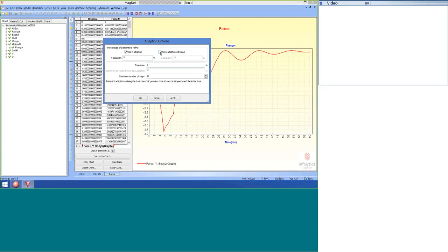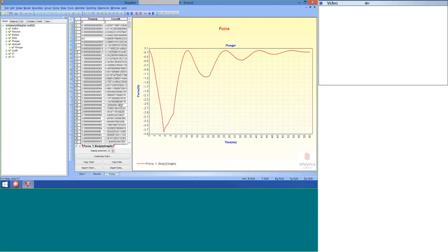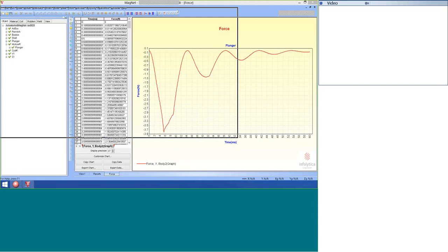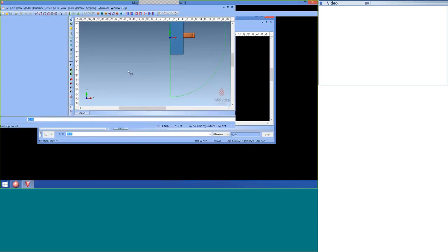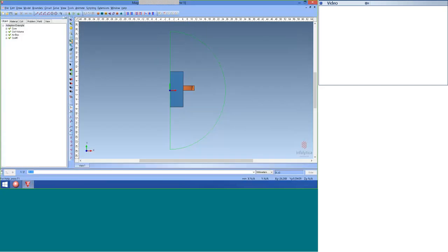And in 3D, we also have P-adaptation, which is where those elements are bumped up in order. We can also have HP-adaptation, which allows you to start by doing some H-adaptation and finishing off with some P-adaptation. So let me bring up a model that shows that, and we'll quickly show you what the effect of doing that is like.